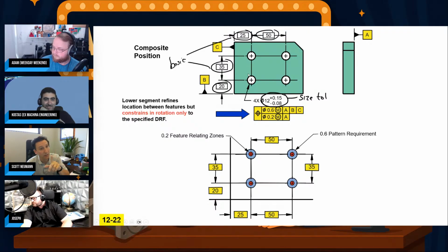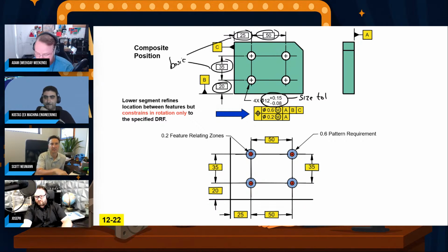Yeah, and that's been like that since 1982, actually. 1982 is when they first said, hey, you should use basic dimensions here. Stop screwing around with that plus minus tolerance. But if you use both, it's a nightmare, isn't it? Oh, yeah, to actually check whether you're in spec or not. People think GD&T is in addition to plus or minus, but no, it's a replacement. Position and profile replace plus or minus. It's the successor to the older system. Yeah, exactly.